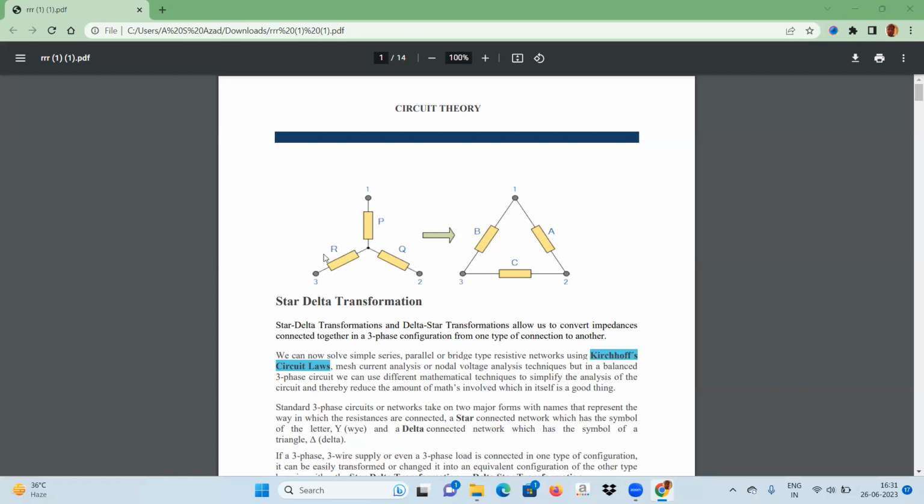The most popular advantage of a star connection is the grounded neutral point, by which any fault current in the circuit goes to ground and the circuit remains safe. This advantage is not available in the delta connection. The other most popular advantage of the delta connection is the reduction of harmonics.